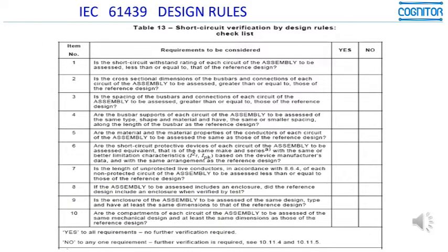We have the so-called design rules. This was the important concept added to IEC 61439. It's a concept in the direction of avoiding the repetition of tests. As said before, the idea is that when you test one first equipment, which we will call the head of